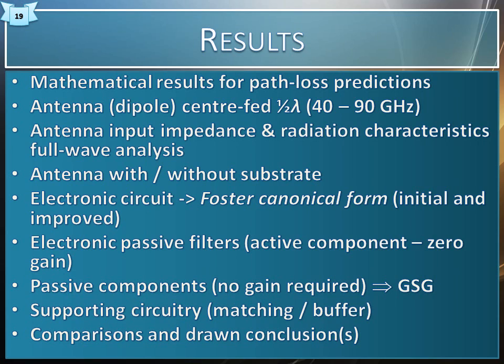The simulated antenna results are used to determine the transfer characteristics of the antenna's real-world operation and use the acquired data to formulate the equivalent circuit. The electrical circuits. The results of the electrical circuits designed in schematic and layout using Cadence and prototyped in a 130 nanometer node. Results are presented and compared to the previous simulations.